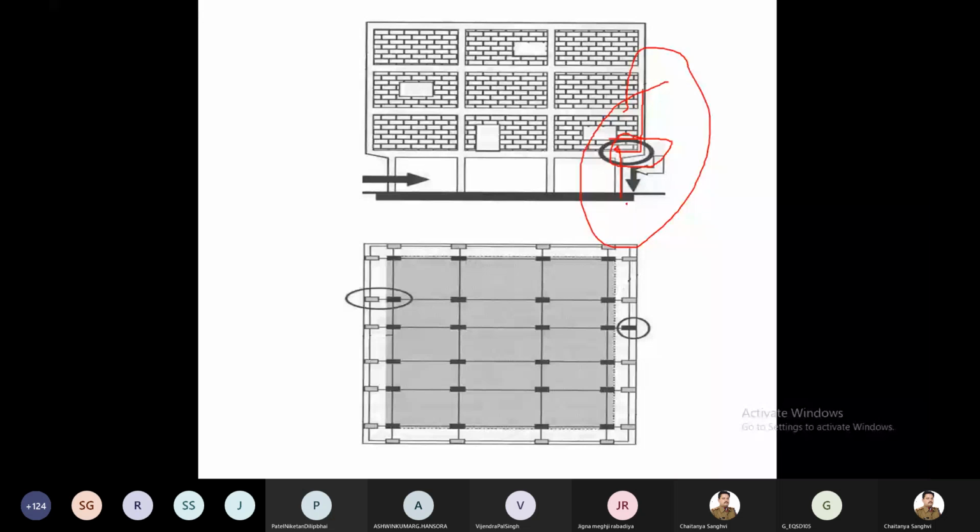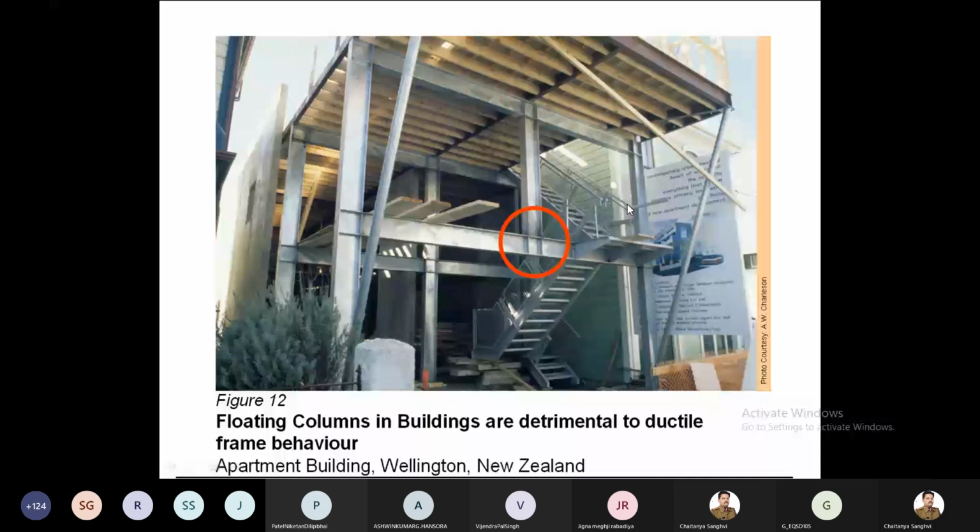Now here you can see, we need a larger opening here, right? We need an opening. So this column which is here is resting on this beam, right? So it is transferring load like this. This is not a good load path. The load path must be good enough. I am always saying that forces flow like water, right? If you design like that, your structure is good.